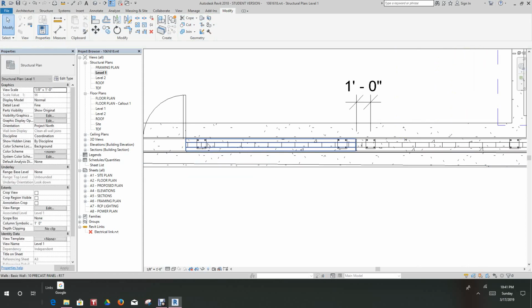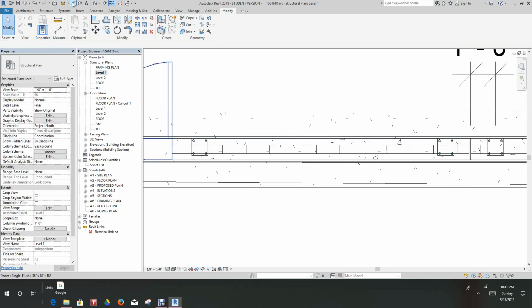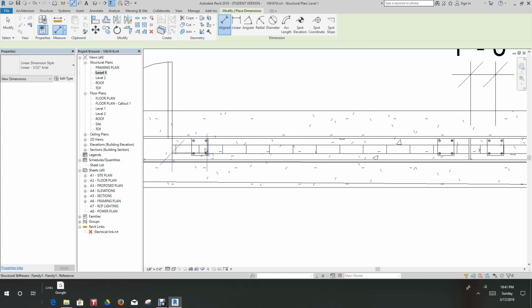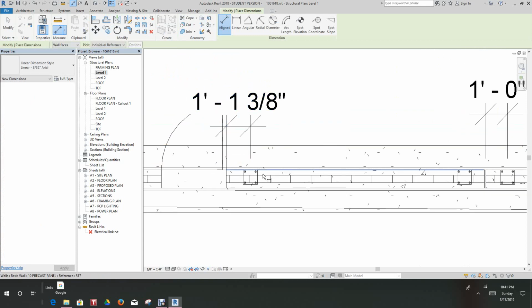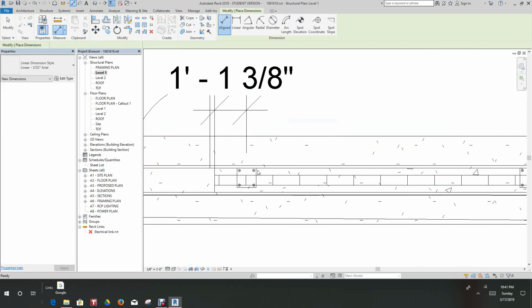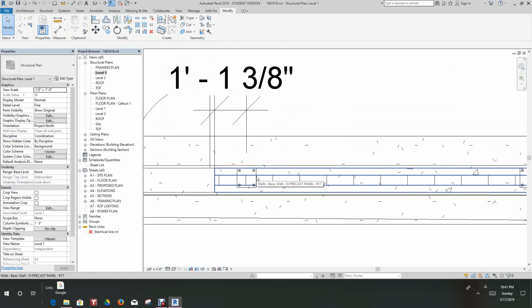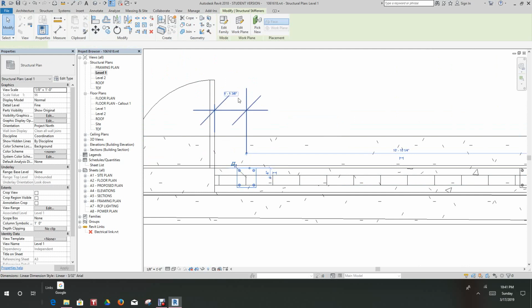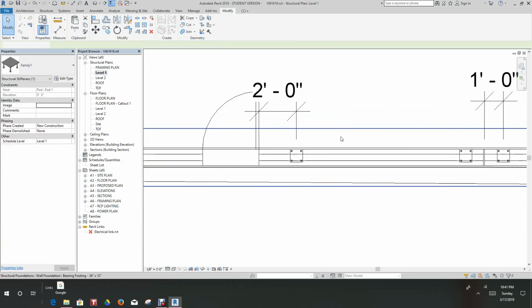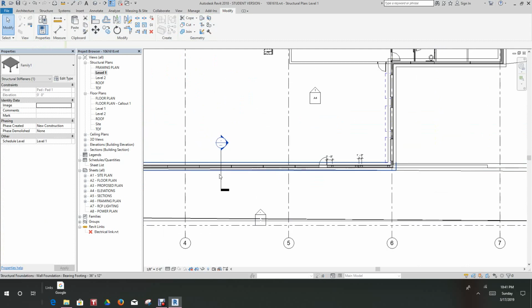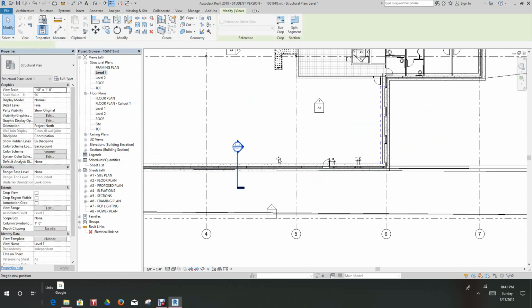We'll select this plate. From the edge of the door to the plate center line, let's make this 2 feet, or whatever they require you to do. So let's make this 2. So now you have these plates here. Now let's go and pull this section over and have a look at what we have here.